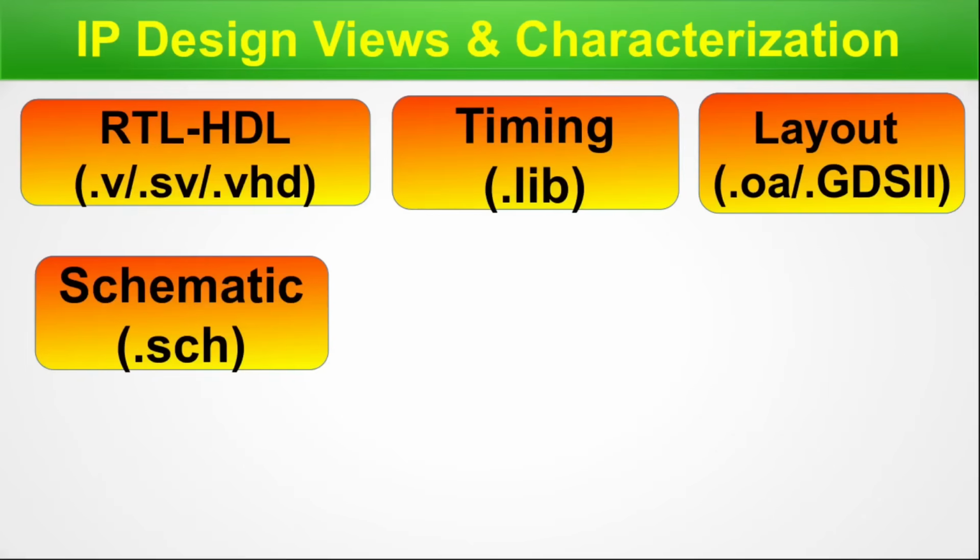The schematic is an essential part of the analog IP design. Here, you have a library of active and passive components from which you can drag and drop components into your workspace. Then, you interconnect them with wire, power source and ground. Then, you add analysis types like AC, DC or transient as per the application of the IP. Thus, you can create and test unit cells of analog IP. You need to have the skill set of Virtuoso or Custom Compiler schematic capture tools. You can also have a taste of the schematic-based free tool LTspice for your practice.